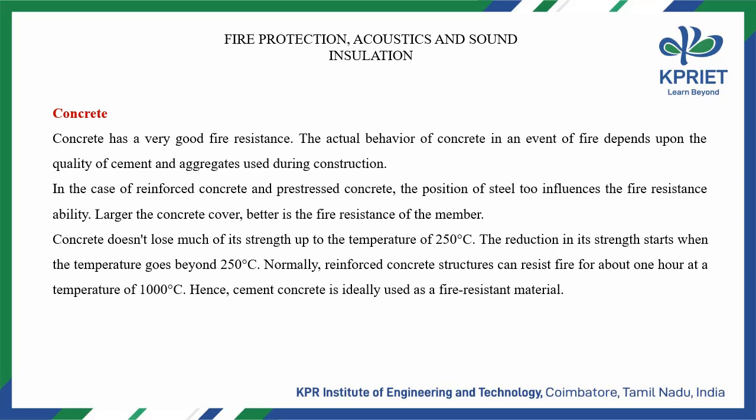Concrete doesn't lose much of its strength up to a temperature of 250 degrees Celsius. The reduction in its strength starts when the temperature goes beyond 250 degrees Celsius. Normally, reinforced concrete structures can resist fire for about 1 hour at a temperature of 1000 degrees Celsius. Hence, cement concrete is ideally used as a fire-resistant material.